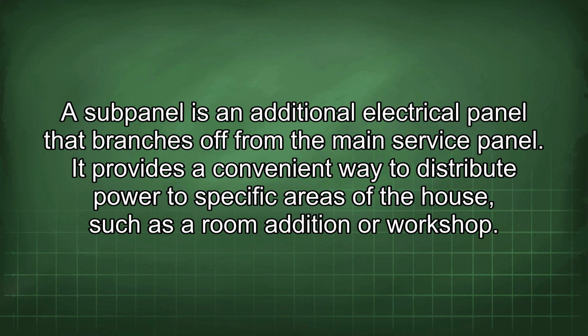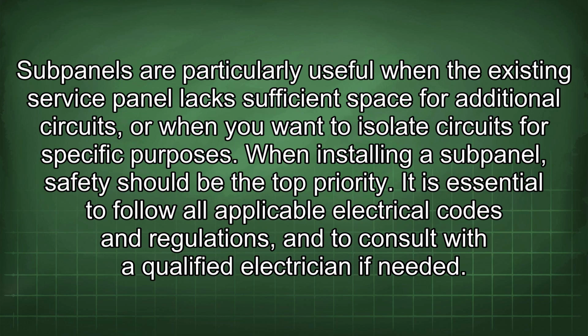A subpanel is an additional electrical panel that branches off from the main service panel. It provides a convenient way to distribute power to specific areas of the house, such as a room addition or workshop. Subpanels are particularly useful when the existing service panel lacks sufficient space for additional circuits, or when you want to isolate circuits for specific purposes. When installing a subpanel, safety should be the top priority. It is essential to follow all applicable electrical codes and regulations, and to consult with a qualified electrician if needed.